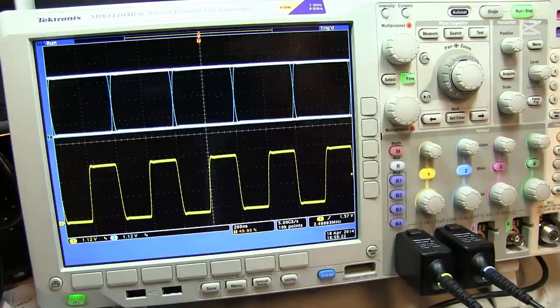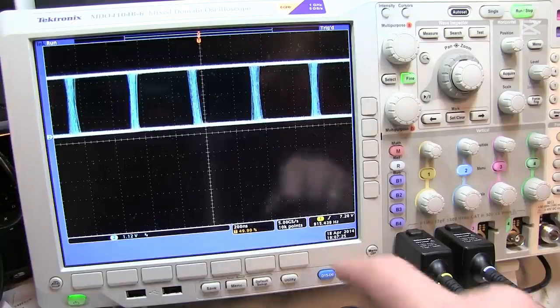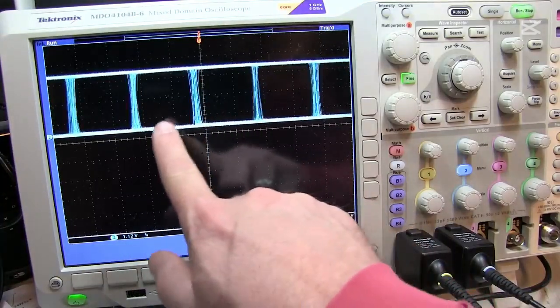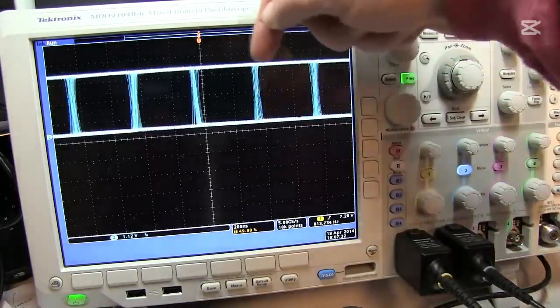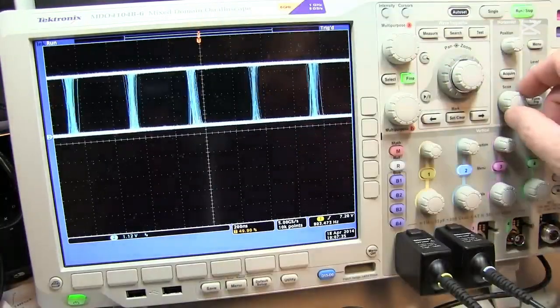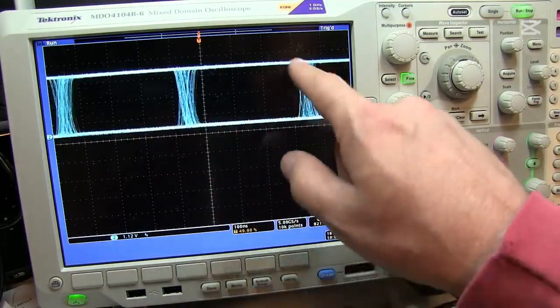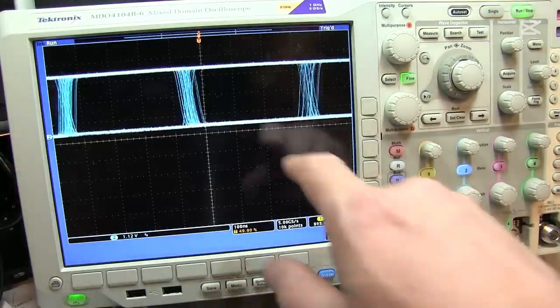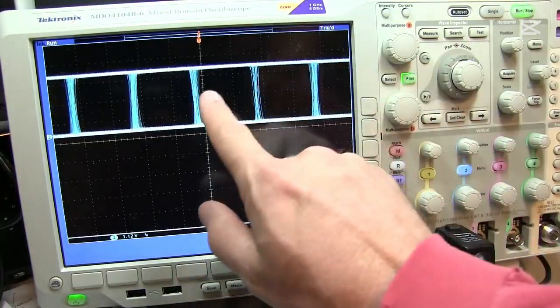Now if we add some distortion here, our eye diagram will look like this. You can see that there is some distortion in the crossovers on the reference axis. We are still able to make out what is happening here. You can see that there is noise, but it is still an open eye diagram. Perfect.